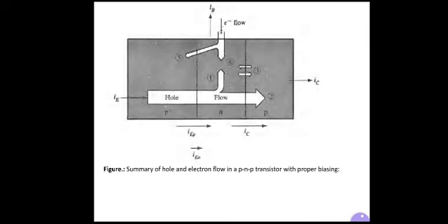In an NPN transistor, the three current directions are reversed. We have discussed the PNP transistor. In an NPN transistor, all three current directions, emitter current, base current, and collector current, are reversed, since electrons flow from emitter to collector, and holes must be supplied to the base. The physical mechanisms for operation of an NPN can be understood simply by reversing the roles of electrons and holes in the PNP, whatever we have discussed.